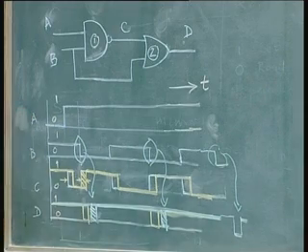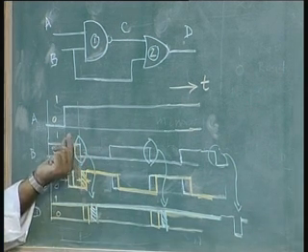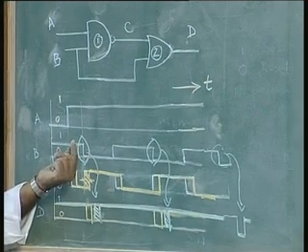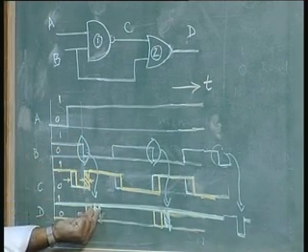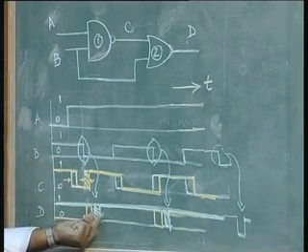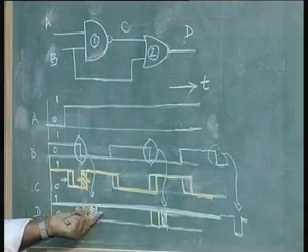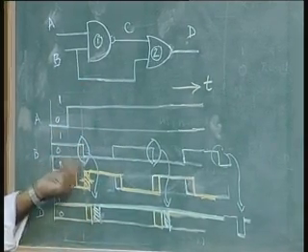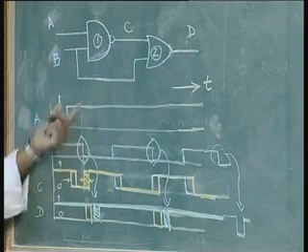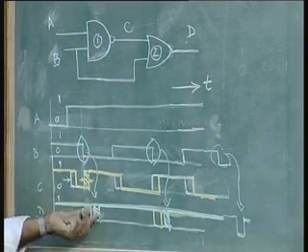So, what I want is, corresponding to the input which is constantly 1, the input to be a narrow pulse every time the clock changes. Every time the clock changes, in this case from positive to negative, that means negative edge, the output becomes a small pulse. Now I can change this into a positive pulse by, as I said, changing the configuration of the gates. I can make this pulse positive edge triggered by again making some changes in the circuit.